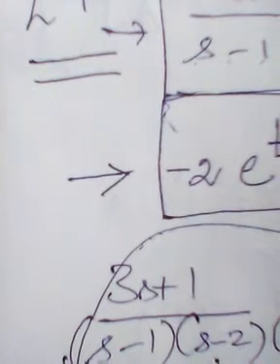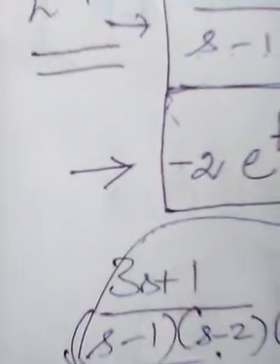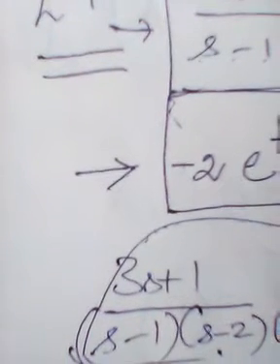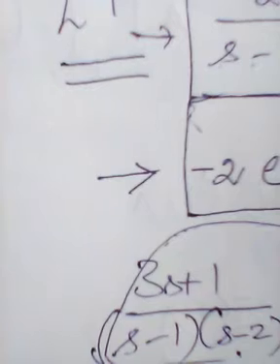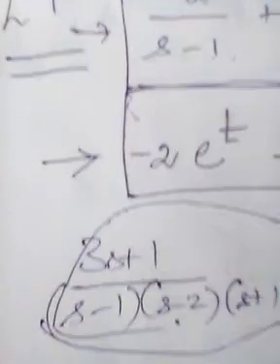So when we want to analyze the control system part by part, then we can say that the pole corresponding to that part, which is located on the right hand side of the plane, is going to create instability. So that particular portion of the control system has to be adjusted such that it is not going to create any further complexity in terms of instability.